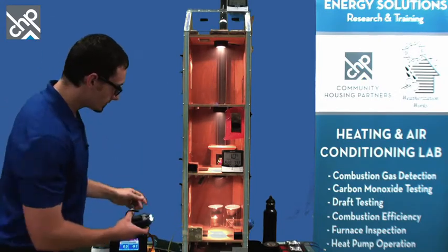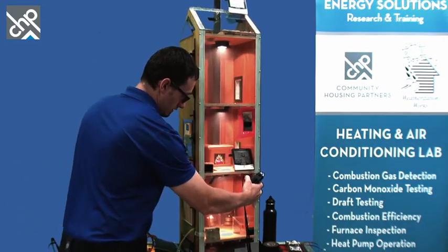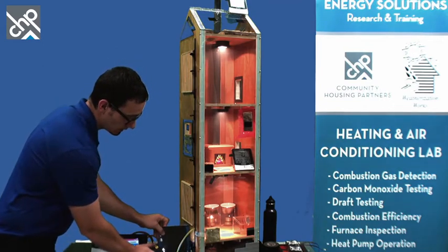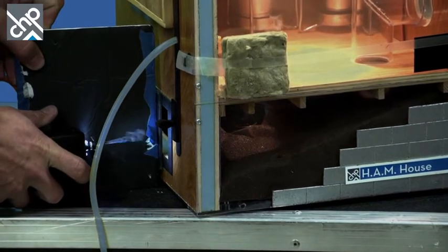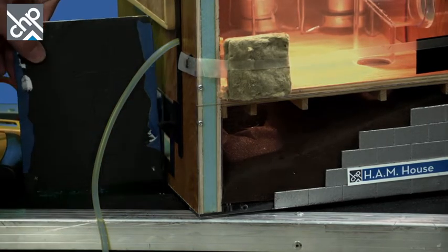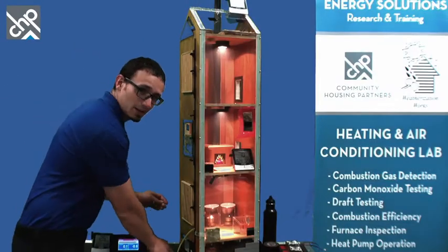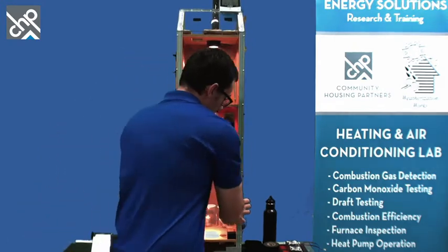So now, if I turn this over to the side just a bit, you can see the same relationship just in reverse down here at the bottom. Now that air is being drawn in from the outside in the crawl space and going where? Going right into the house. So if you think about that from an indoor air quality perspective, it's not a good thing. Definitely not a good thing. Let me kill my smoke here.